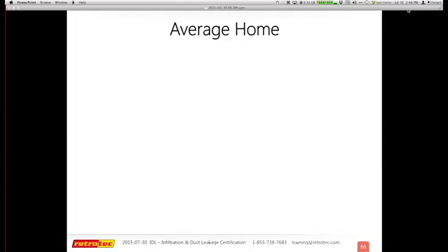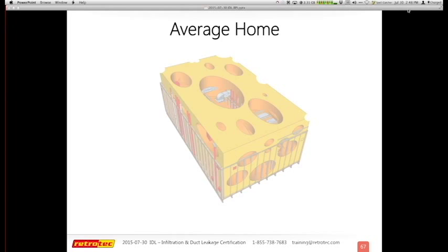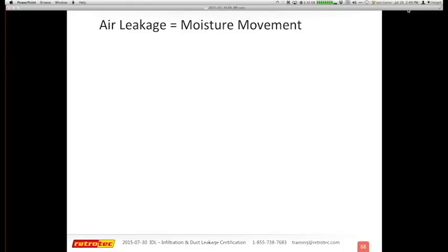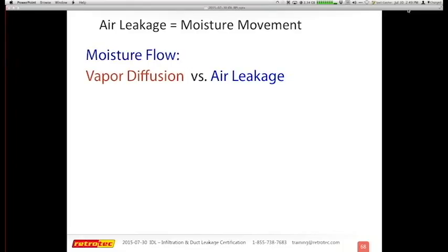So the point is that we actually do have issues from outside to inside and internally. There are an enormous amount of connections that go through top plates and other connections to the attic or crawl space, and large ductwork moving through floors. All those things create an enormous amount of energy and air moving throughout the interior of the structure, let alone the outside of the structure. So there are multiple reasons to be controlling our air movement and flow.